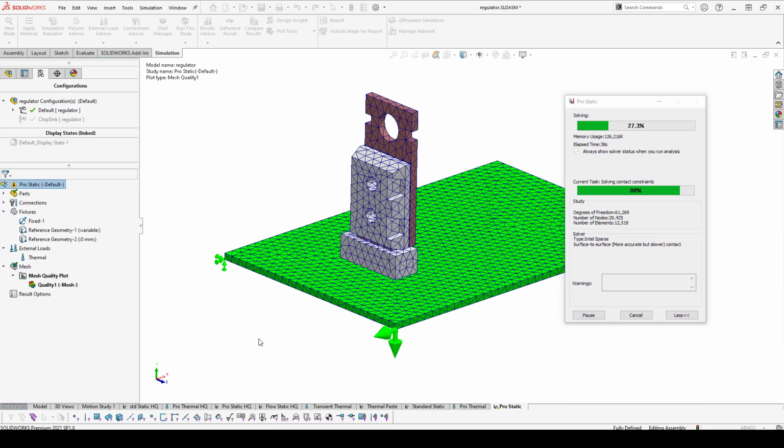Now, it's an important effect because if I just bonded this stuff together, we wouldn't see that this body here and that body there wouldn't be able to slide apart from each other a little bit like they'd be able to do in reality if things are expanding at different rates. If you bond them, you'd see more elevated stresses in some of those regions.